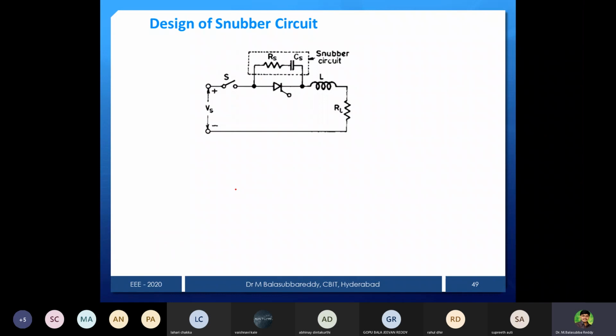In the later classes, we will see that adding only the resistance is sufficient, but the problem is while it is recharging, it goes through the resistor. It's fine, but while it is charging, what will happen when the switch is closed? That current has to pass through the resistance while charging the capacitor, plus and minus, it is going through the resistance.